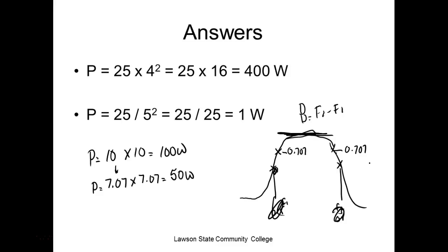A lot of people ask, what would the voltage be if the voltage drops down to 1/2? Everybody wants to think the power is going to drop to 1/2. So this is 70.7% of voltage or current, because current and voltage are proportional, right? But current is not easy to measure either, because to truly measure current, what do we have to do? We have to break the circuit and make the current flow through the meter.